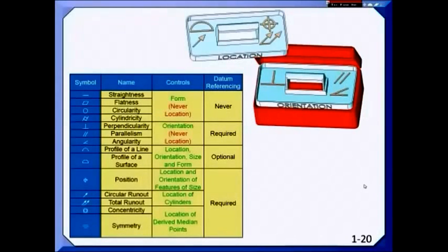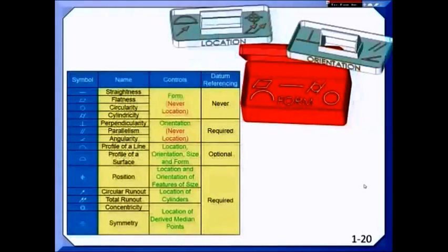And then, only if necessary, might you go further into the toolbox to pull out the orientation tolerances. You got them for free with location, so the only reason to get the actual orientation tolerances is to tweak what you already have controlled. And once in a while, you have to dig way down into the toolbox for the form controls, and yeah, we put profile of a line down there. Because we get form control for free with size tolerances, many times with locating tolerances like profile, and with the orientation tolerances on surfaces. So it's rare that you need to dig way down into the toolbox.